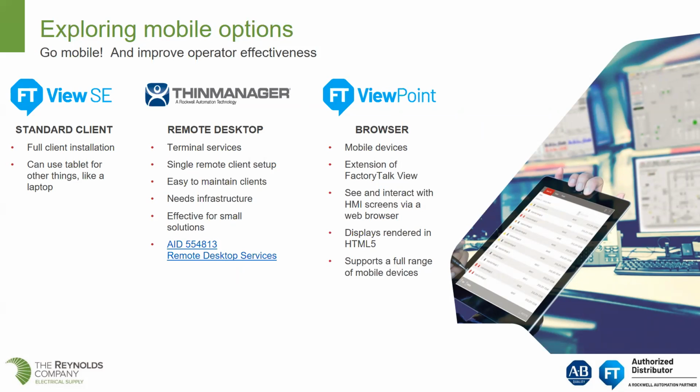We could deploy thin clients throughout your facility. Right now you have individual RSView32 applications running in your facility, and we could convert all of that over to thin clients. The advantage to thin clients is you do not have operating systems running on the factory floor. So there are no Windows updates going on your factory floor with thin clients.